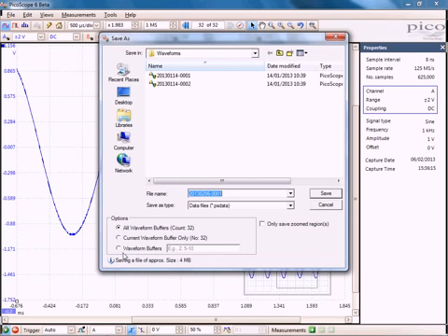In addition to saving all waveforms and the current waveform, you can also specify the buffers you want to save. So for example, in waveform buffers here, I can select buffers 1 to 5 and 12. Another great addition is saving only the zoomed in region, and this will apply to any of the buffers selected. This will give you greater flexibility over your waveform storage.